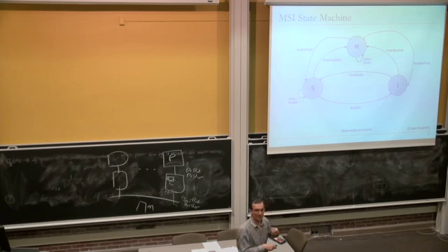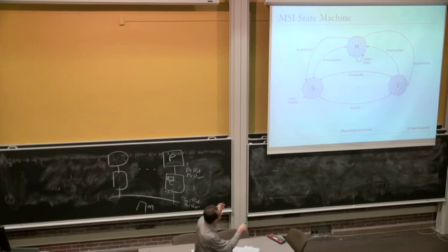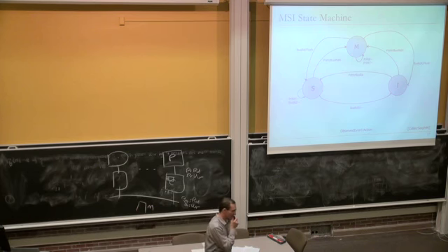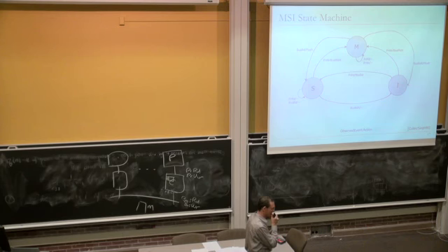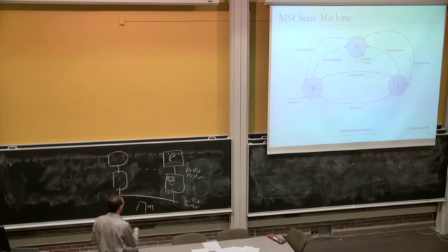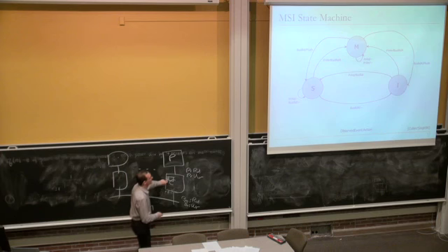Does that make sense? I'm not going to go through the protocol in detail because it's relatively simple. We discussed this. But do you see any problem with this? Yes? You don't have the exclusive state, so when you bring it in, it'll first have to come in the shared state, and then when you want to write, you'll have to send out the bus readx. That's right, yeah. So let's say this processor has the only copy of this cache block in the system.